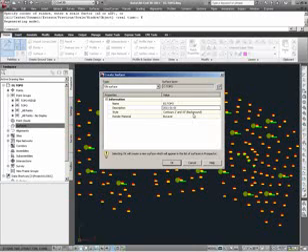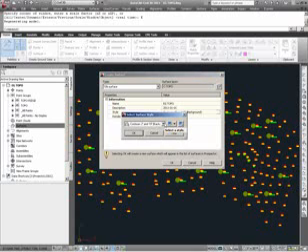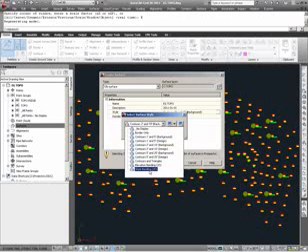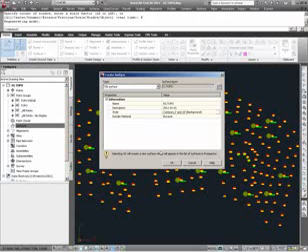And finally, under Style, we find that when we build a Civil 3D surface model, we must choose a style which will constrain how the surface will appear in our drawing. Currently, the surface style is set to a style which will show us contours that are at 2-foot and 10-foot intervals and will apparently display as background contours, such as contours for an existing grade surface. Should we want to change this, we could simply click in this field, and choosing the ellipsis button, we have the Select Surface Style dialog. Here, we are going to stay with the same surface style that has already been selected.